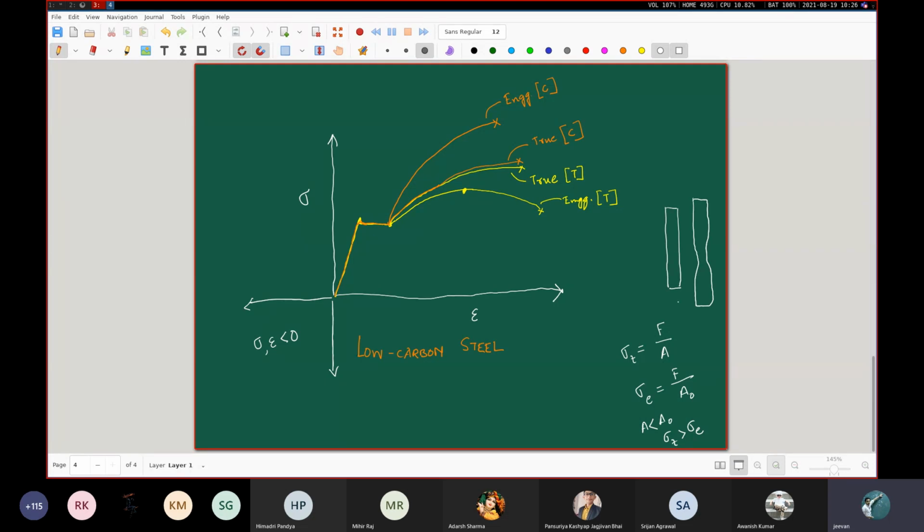Now, when you are pulling at the two ends, and if those micro cracks are present, there is a chance of those cracks enlarging. So you are not actually helping its cause to maintain its structural integrity by pulling against the crack. Suppose you have a sheet of paper in which there is a slight perforation in the middle, and then you are pulling at the two edges of the paper. That paper will barely be able to sustain your tensile forces, your pulling forces. It will just tear apart.